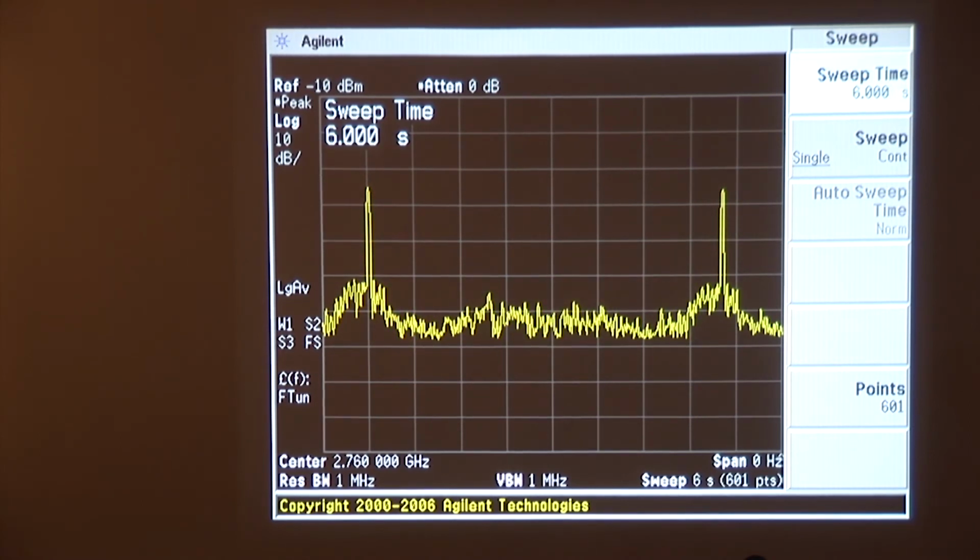If we were to watch this radar over and over, we would find that this interval is always the same, and we're seeing no other beam scanning occurring in that interval, so we know that this radar has a simple mechanical rotation, and it probably has a 1 over cosecant squared fan beam radiation pattern, which tells us that it's probably an air search radar.